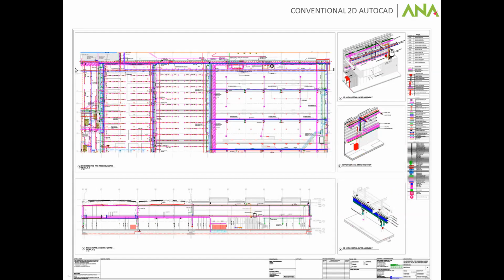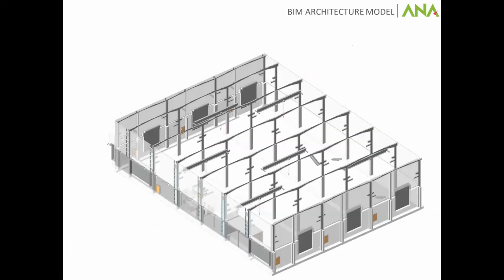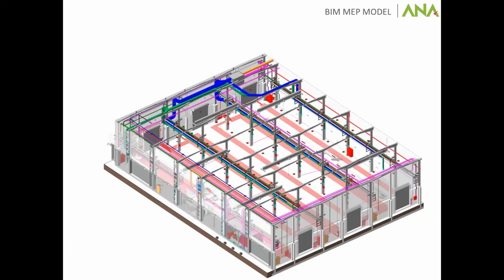Massive difference in the energy consumption and the number of hours of running of the compressors. Apart from that, we also managed to work with various companies, notably Blue Box and its associated companies, to actually use radiant cooling in the floor. So what we've done in this building is that about 270,000 square feet of the industrial floor has PEX pipes